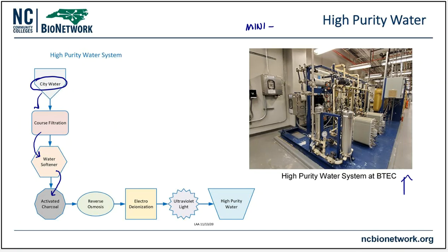Next up, once that is now super clean, it can then be processed more easily through reverse osmosis. And this is that membrane that we discussed, and only water will be able to escape through that membrane and out the other end. We want to take care of as much contamination as we can leading up to this process, because the more of it that remains at this stage, the gunkier that reverse osmosis filter is going to become, and you're going to have to change it out more, and they're not very cheap. So if I can clean up my water pretty well up until this point, then that RO system can last for quite some time, and we don't really get any kind of problems out of it at all.